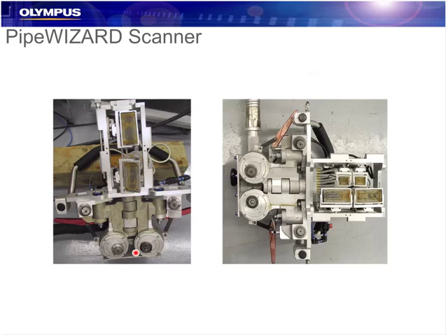On the left, we're looking at the underside of the scanner. We can see how small the carriage is when we only use 2 phased array probes to be able to get full coverage of the weld. Often we'll use a larger carriage and we can add time of flight diffraction. And other slides will also show some other adaptation for other ultrasonic needs.